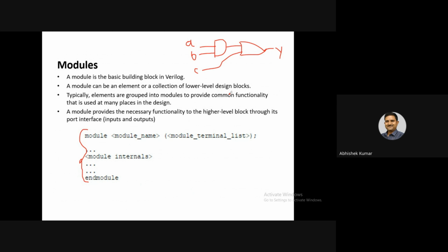Now whenever it is asked to write the program for it, we can start like this. The first word is module. Remember Verilog is a case sensitive language, so do not mix small letters and capital letters here. The first line of the program will be module space, and then we have to provide the module name. Module names are user specific. Suppose I write the name of the module as temp.